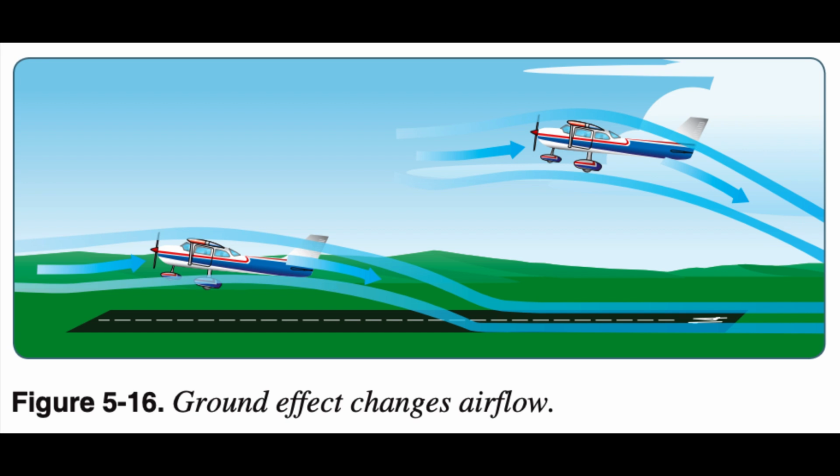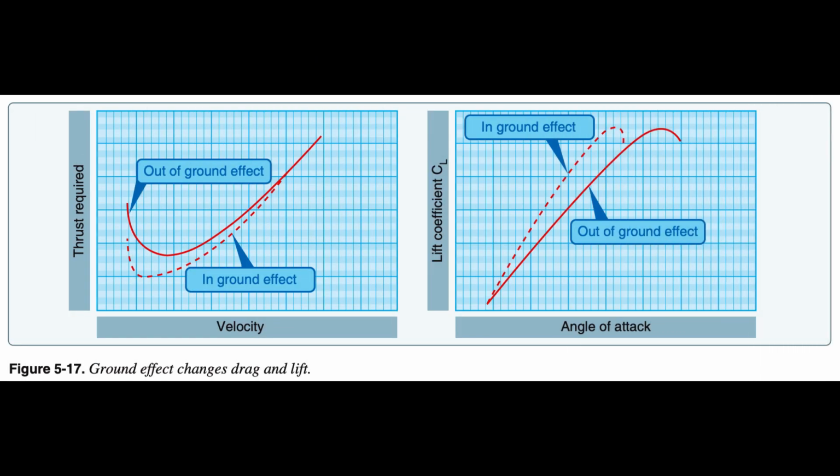downwash, and wingtip vortices. Induced drag is a result of the airfoil's work of sustaining the aircraft, and a wing or rotor lifts the aircraft simply by accelerating a mass of air downward. It is true that reduced pressure on top of an airfoil is essential to lift, but that is only one of the things contributing to the overall effect of pushing an air mass downward. The more downwash there is, the harder the wing pushes the mass of air down. At high angles of attack, the amount of induced drag is high. Since this corresponds to lower airspeeds in actual flight, it can be said that induced drag predominates at low speed.